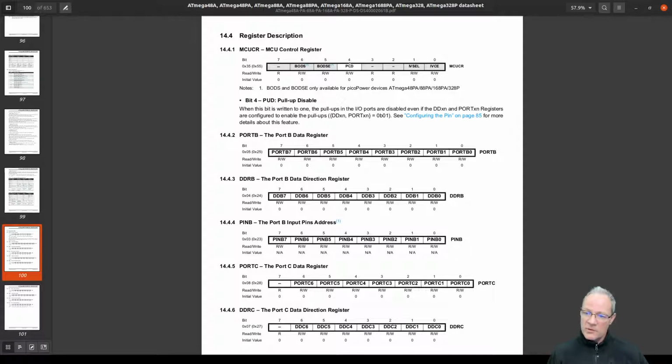Only when you read from those pins you can enable pull-ups, do the reading, and then disable the pull-ups. Right. So once again, what we notice here is that we can manipulate the power consumption from the program if we know the structure of the processor and the features that it provides.